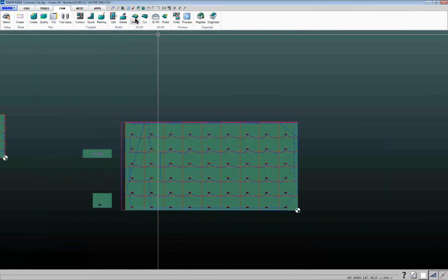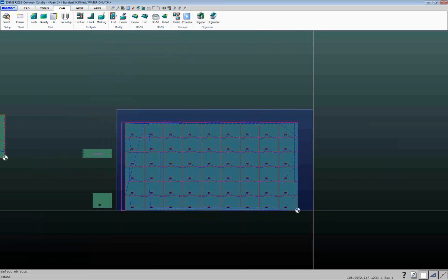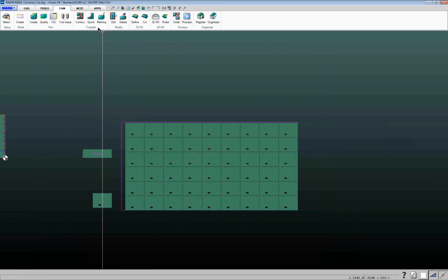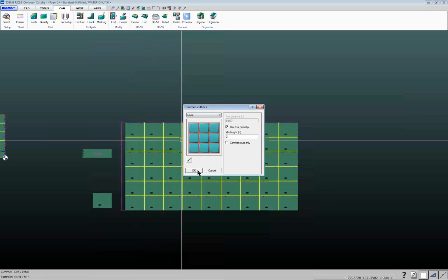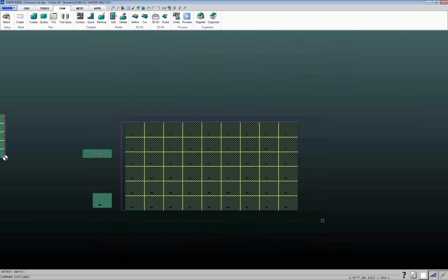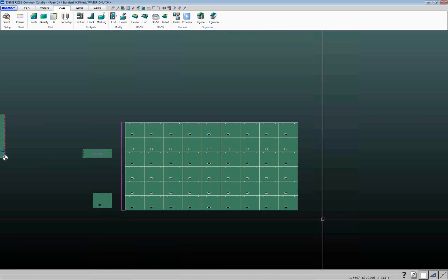And then the other option that's in there, which I've found rare instance to use, go into common, they've got the lines option. So this will basically make CAD lines that you could then copy if you want to create a DXF file, bring it out to another software package or something.